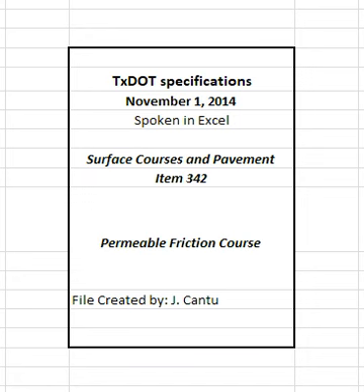4.4.2.2.4 Ignition oven correction factors. The engineer will use the split samples provided by the contractor to determine the aggregate and asphalt correction factors for the ignition oven used for QA testing during production in accordance with Tex-236-F. The engineer will verify that the asphalt content correction factor takes into account the percent fibers in the mixture so that the fibers are excluded from the binder content determination.